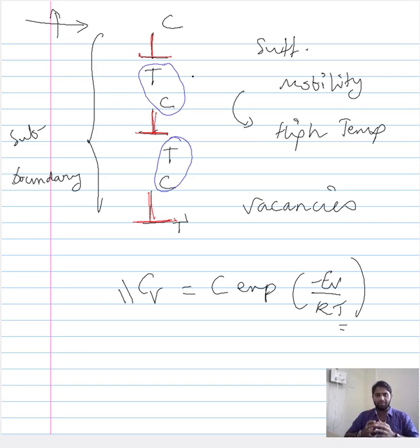So what we have done is, by introducing high temperature, we have increased its mobility, thereby enabling the dislocation to glide, and we have also increased the vacancies, so the dislocation can climb. Therefore, we have provided the energy for dislocation to rearrange themselves to reduce the overall energy of the system, and they have arranged themselves in this manner, and because the tensile and the compressive components compromise with each other, they compromise the energies. So you ultimately end up with a low energy state, by forming what we call the sub boundaries.